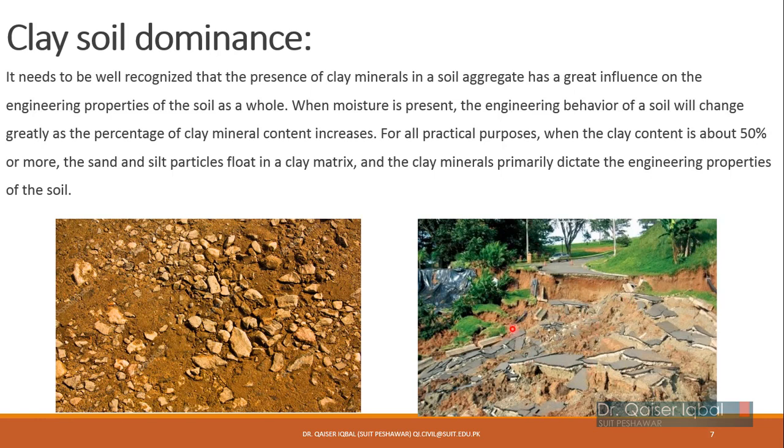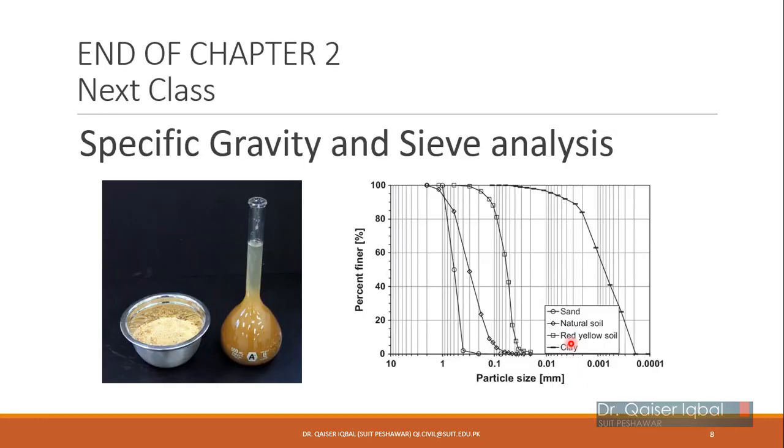Clay can expand and contract upon wetting and drying, and its shear strength is very poor as well, which can result in failure. So we have to be careful, and wherever there is clay, we need to identify it and design our structure accordingly.